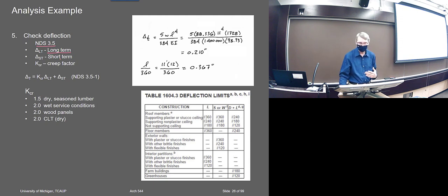So on something like a live load, most of it's probably short-term. The biggest part of the load in here is probably you people coming in and out, and you're gone at the end of class, so that's not a very permanent load. The other part of the live load would be the tables, or maybe the carpet. It's not quite that much load. So depending on your application, you make some sort of a judgment.